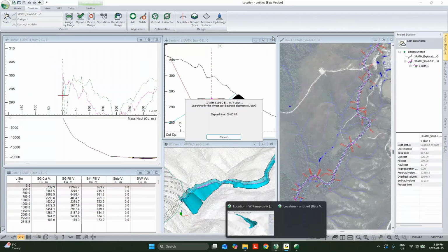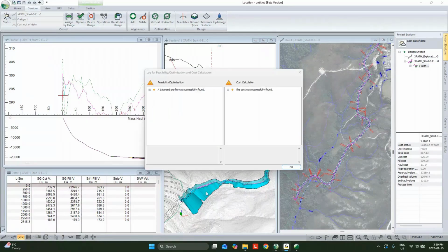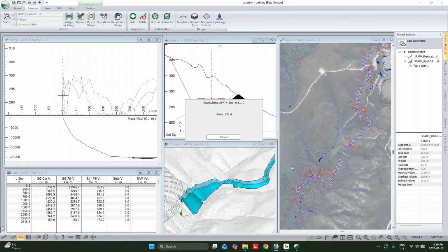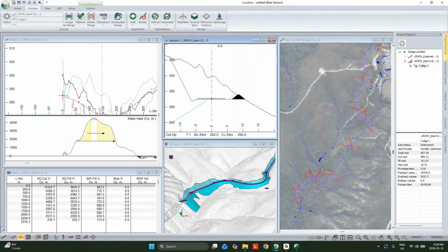And the other thing you could do that kind of goes hand in hand with that. So if it's just the benches and the pit itself that you wanted to add in, you could do that as just a back slope on the berms, but otherwise you could just select the outside edge of your benches, buffer them up to give the top a berm, buffer it over, and then buffer them down. It would be fairly painless. But yeah, and we've got a solution.